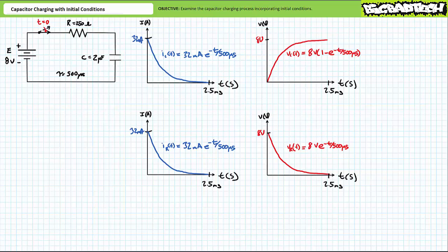You'll note voltage for the circuit never exceeded 8 volts. If left to its own devices, the final voltage for the circuit would always result in an 8-volt differential being applied across the fully charged capacitor after the passage of 5 time constants, in this case 2.5 milliseconds.